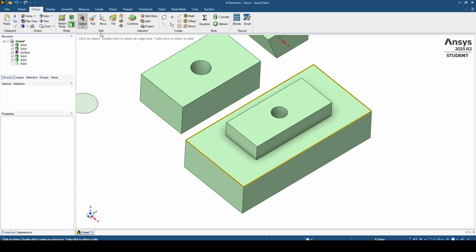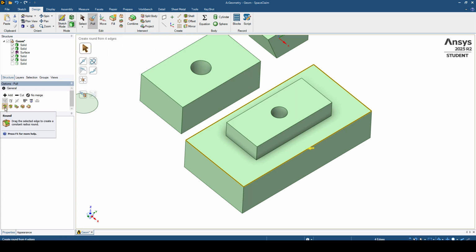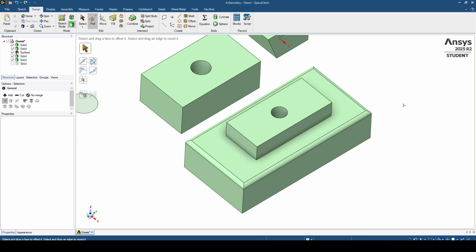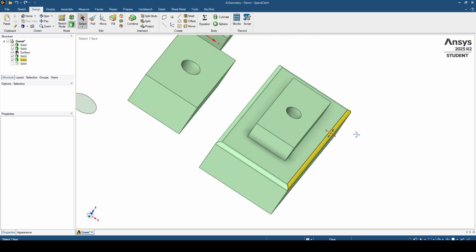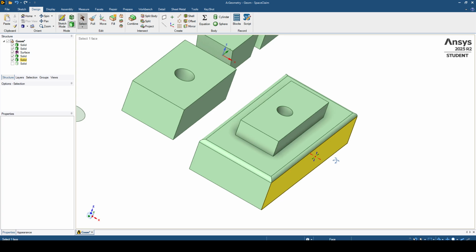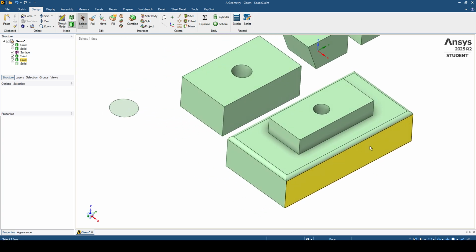We go again to the Pull tool and we have already the fillet feature here, and I type 1 millimeter, so 1 millimeter and click. As you can see right now we have a fillet around these four edges here with 1 millimeter as a radius. It makes our shape smoother and good looking. Now you can also select multiple edges as we can do, and we can do it for the other edges. This is very useful when you want a consistent look across your model.